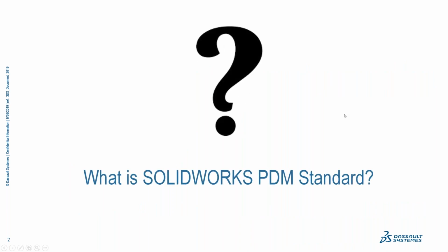So when we're looking at SOLIDWORKS PDM Standard, and what is SOLIDWORKS PDM Standard, before I answer that, I would like to ask you to think about how you currently store your data. You might have it on your local drive or on the network. And what happens when you start collaborating with other users and somebody opens an assembly, for example? All your components are now locked and nobody can modify them. And how about when you are making a change and you want to revert back to the original model?